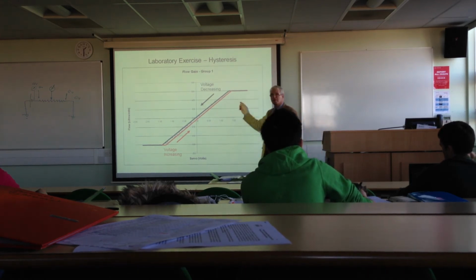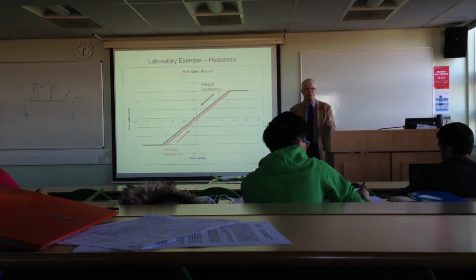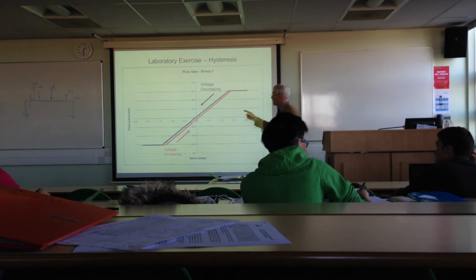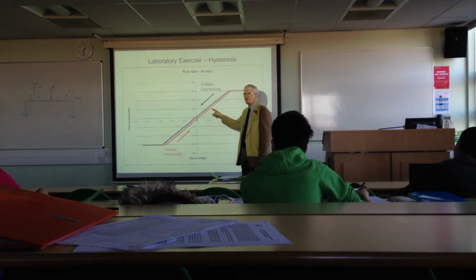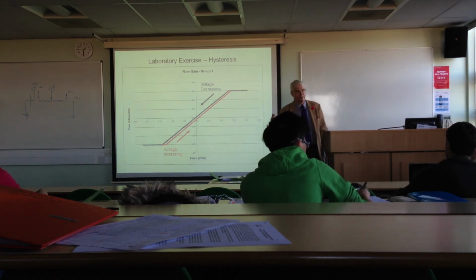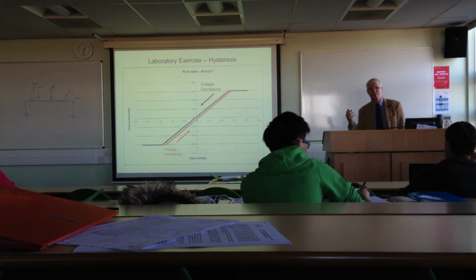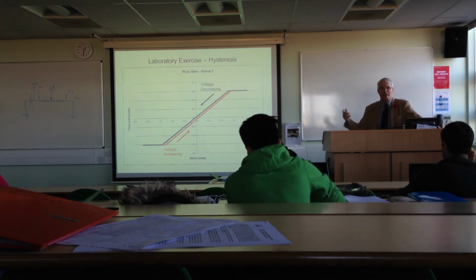Now that could be that the spool is sticky. In other words, you have to put a positive voltage to actually get it to move. So if we were here, you'd have to do a jump in the voltage before anything would happen, or the other way. Now again, look at your results, and you probably think, I'm going to have exaggerated that, which I have. But that might be another reason.